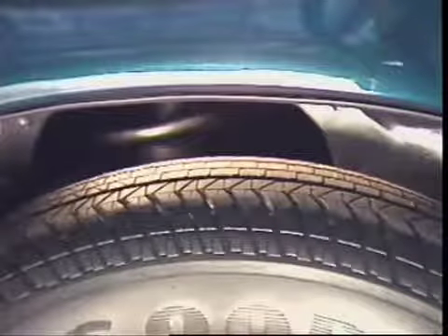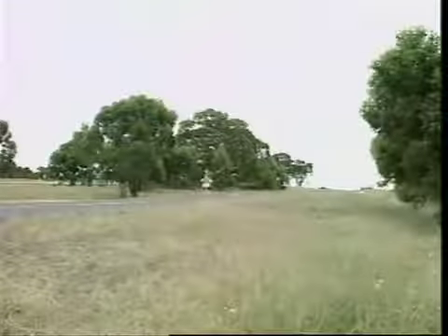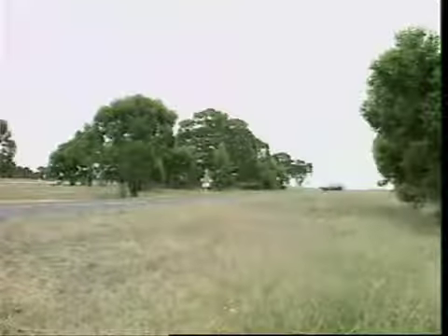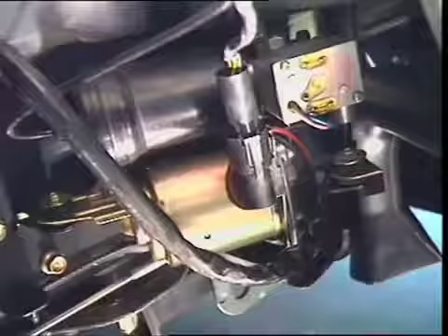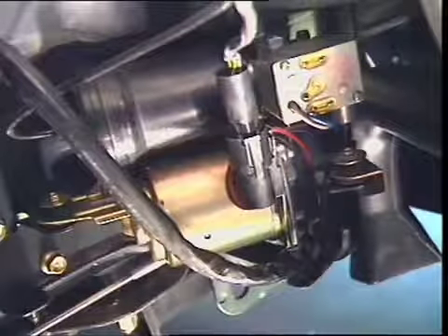If the load is removed, the suspension springs expand, raising the height of the vehicle. The ECU senses the raised ride height, and air is exhausted from the shock absorbers, causing the airbag to deflate and lower the suspension to the normal trim height. During normal suspension operation, continual adjustment of vehicle ride height is prevented by a time delay in the ECU. This allows the trim height to be adjusted only when the ECU reads an out-of-trim signal for 5 to 15 seconds. The compressor run time or exhaust time is limited to 2 minutes.